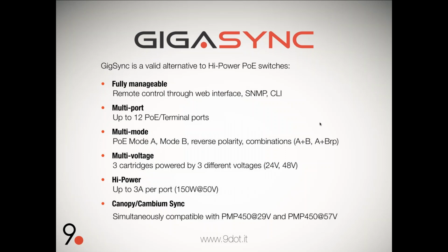It's multi-voltages because we have 3 cartridges in the unit. Each one can be powered by a different power source. So 24 volts, 48 volts, of course, minus 48 volts, just like in telecommunications installation. It's high power because it can give up to 3 ampere per port. It means 150 watts at 50 volts.